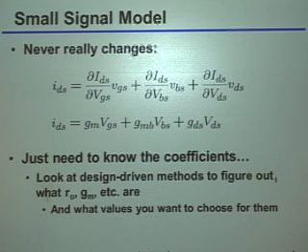So as I was mentioning before, what we're really going to do is come up with a design-driven methodology to really figure out what all of those derivatives actually are. Okay? And not only that, we'll actually show how you could calculate what values you want them to take on. And then once you know that, use, again, SPICE as a lookup table to actually then go and size the device itself. Okay?